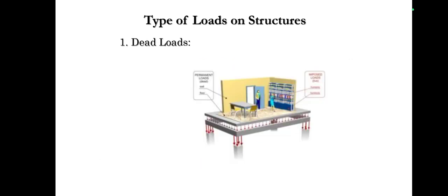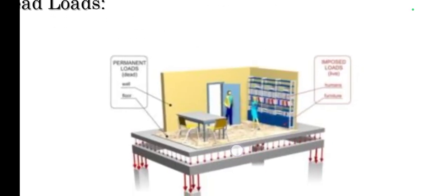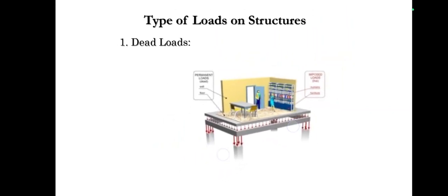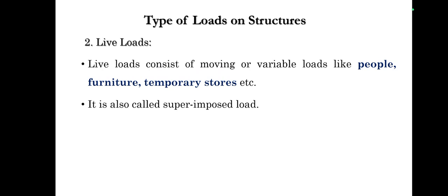So this all acts as a beam. You can see here the slab condition and the beam which transfers to the column. This all comes under the permanent loads, and floor finishes, like the flooring you will be using, also come under dead loads. Okay, next is live load.